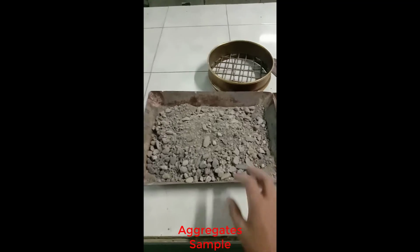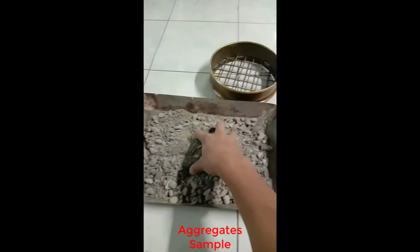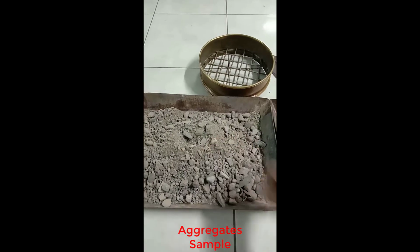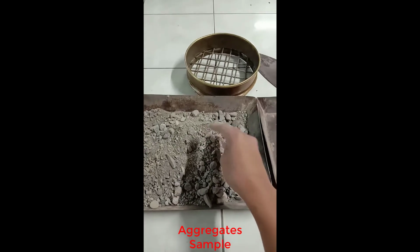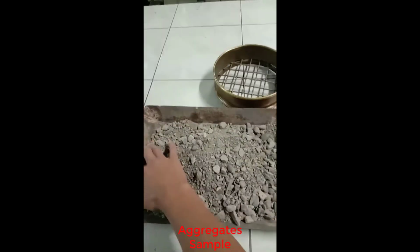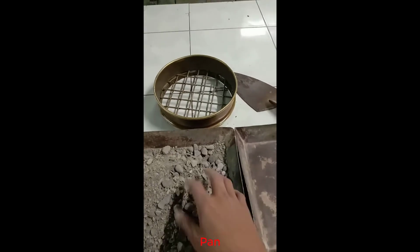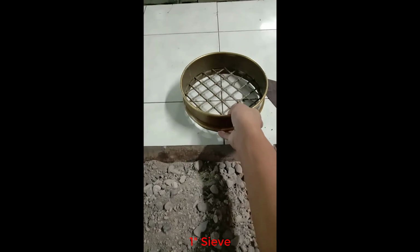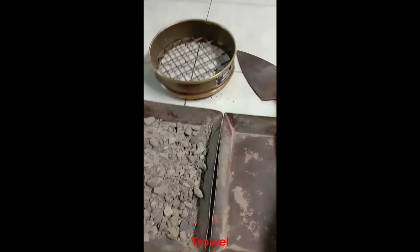So this is the sample that we gathered from the stockpile of aggregates. It is a mixture. It's up to you what you are going to test, if it is a fine aggregate or a coarse aggregate. But in this case, this is a mixture of coarse. It is still a raw aggregate, not separated into fine and coarse. So we have here your pan, and then we have here your 1 inch sieve. This is what we're going to use to screen. If there are sizes larger than 1 inch, we are going to disregard those. And then we have here your trowel.